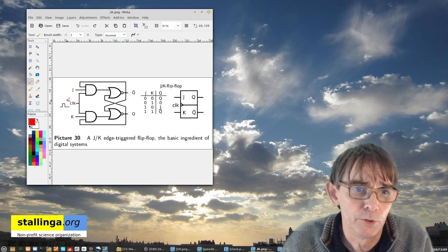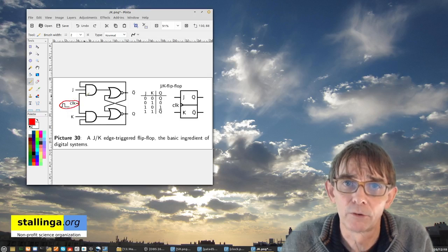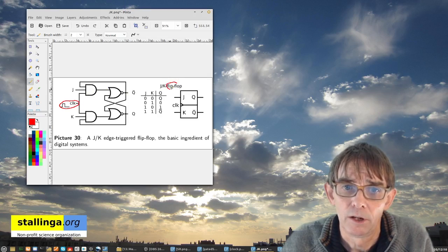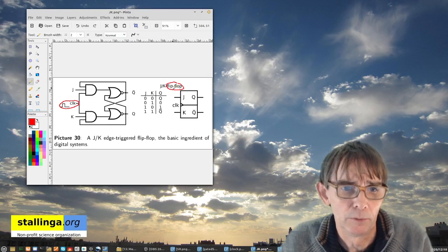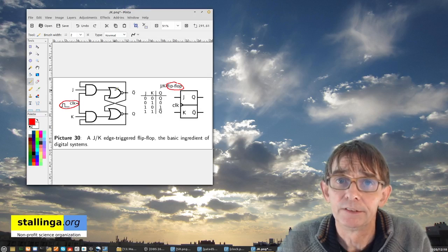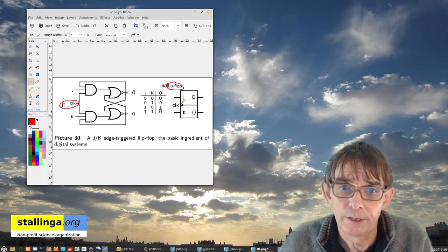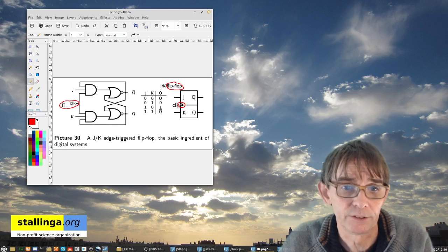And in this case, when we use that trick of ANDing the clock with the delayed clock itself, then we call this a flip-flop. And that is the most famous circuit, in this case, the JK edge triggered flip-flop. We also indicate this by this triangle here. It means it's edge triggered.